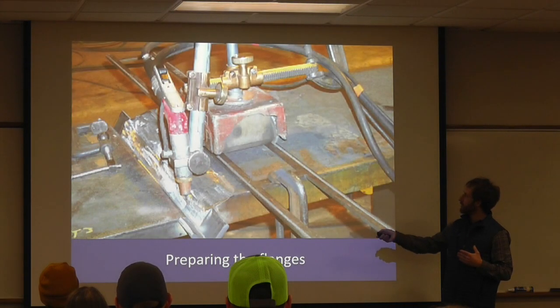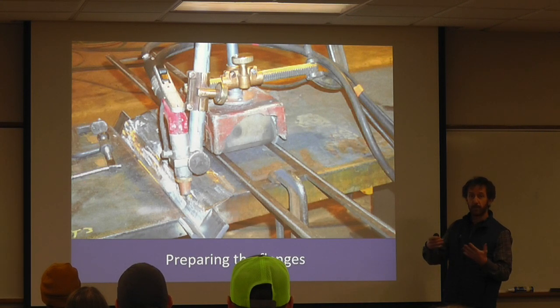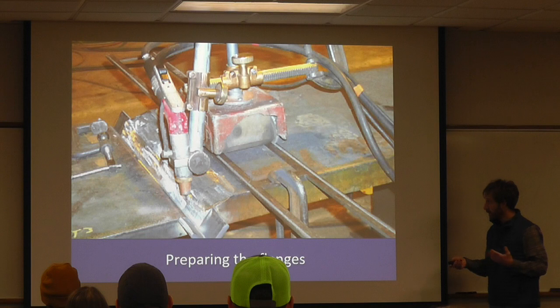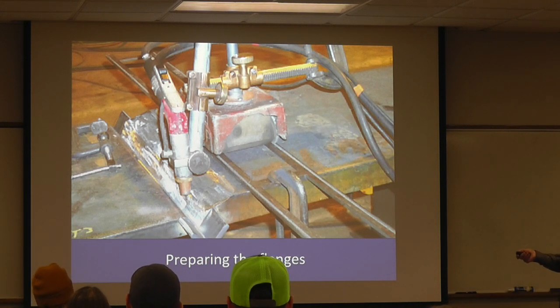So they will come in, and I know this picture is blurry, but they're going to put more or less a chamfer in here to be able to prepare for the weld. We're going to start filling that up with weld. You can see here's that thicker piece versus the thinner piece. This is an automated welding process where they're going to go back and forth and slowly fill up that joint to make a continuous joint weld. Does anybody know why these extra little chunks of angle are stubbed onto the beam? Do we see that typically out in the field?